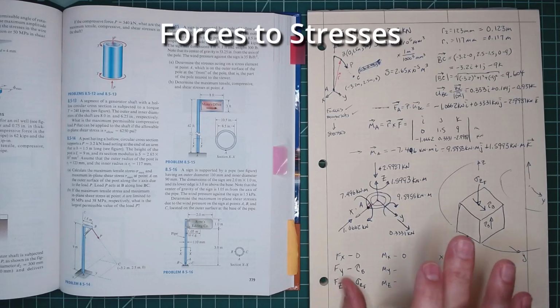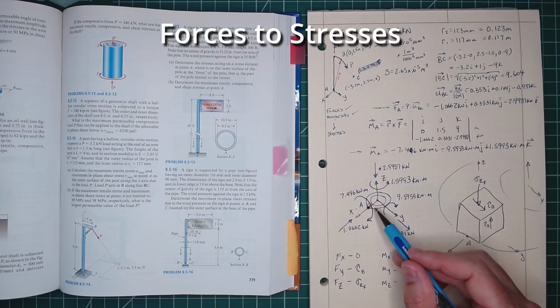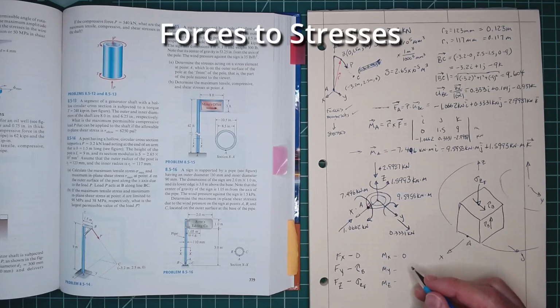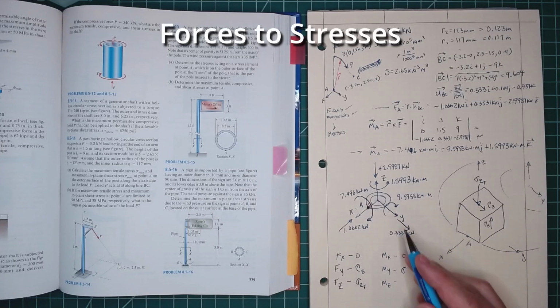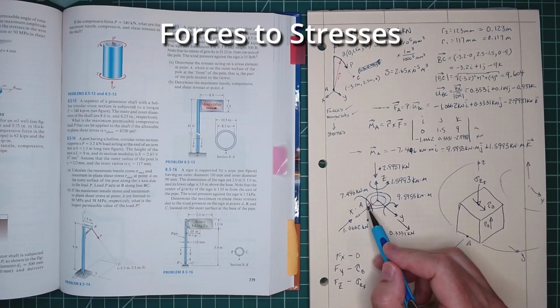For moment in Y, if we look at the bending moment there, the neutral axis is this way, and our point A is at the extreme fiber end. So we are going to get a sigma, an axial stress due to bending at point A. Now, where does this occur?